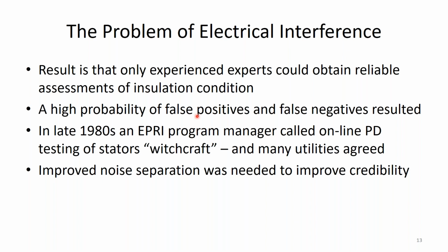The noise was dominating the PD, and they thought the stator winding was in trouble when in fact it was noise. They would run to the plant manager and say, hey, we've got to shut this machine down. There's high PD, it might fail. Although in all my career, and I've looked at data from literally tens of thousands of machines and hundreds of thousands of tests, I've never said shut a machine down based on PD. At least not immediately. And the plant manager then thinks they've got a problem. If they open up the machine and find out there's nothing wrong, there's a credibility issue. That's called a false positive.